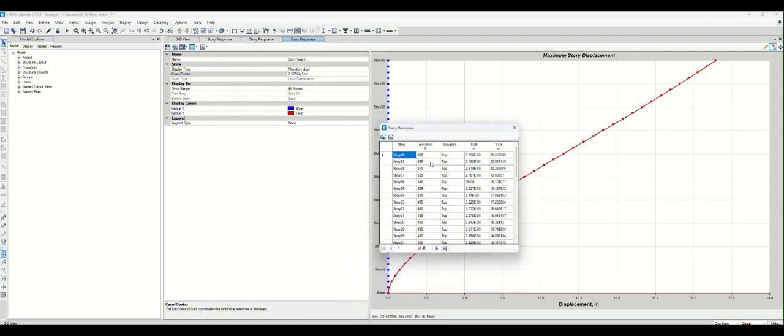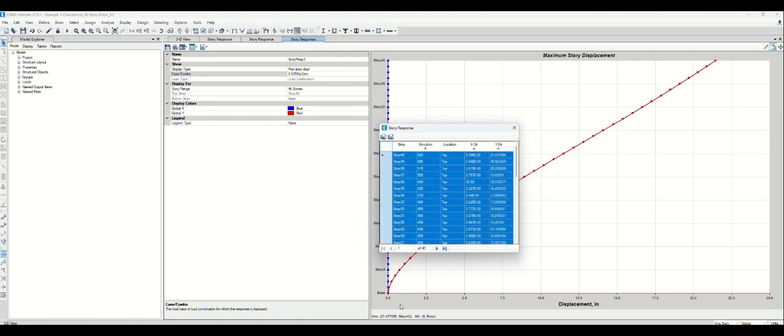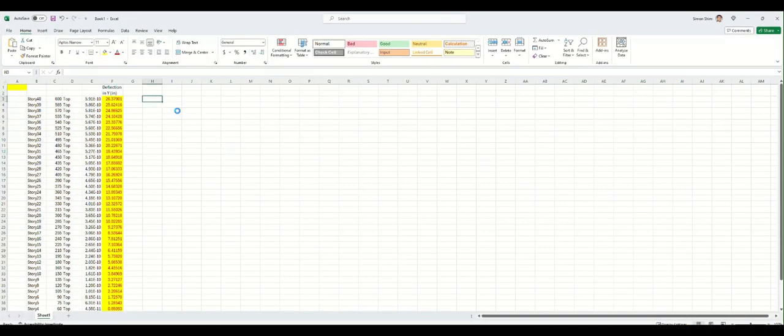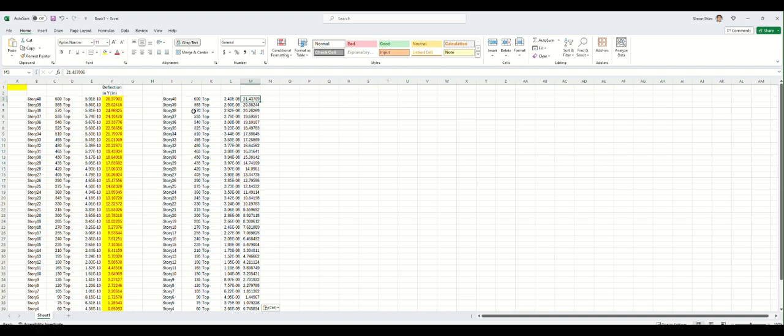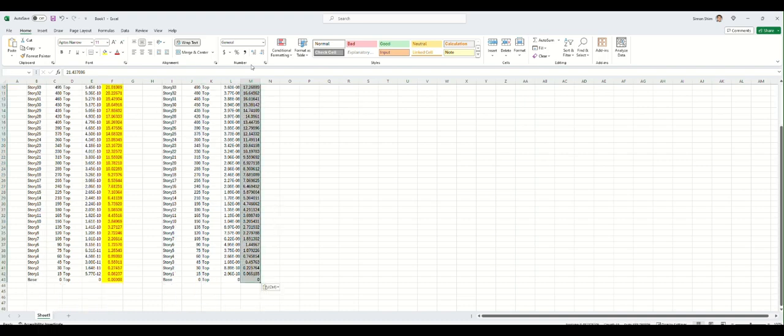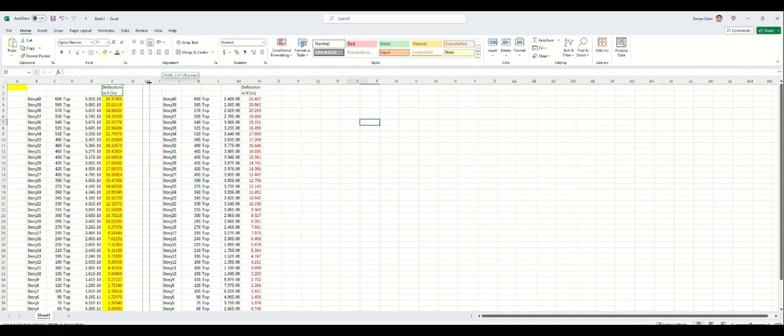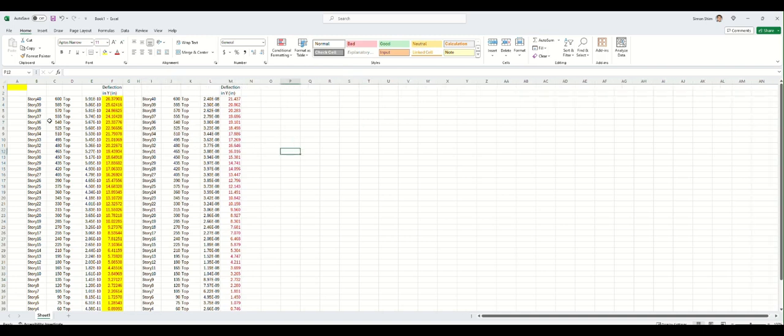Let's say we're gonna select all the data, the deflection in Y direction, Control C, and paste it next to the previous Excel data. So we added. You see the 26 went down to 20. So this is the second model, right? So we need to continuously do this. This is also the workflow until we meet